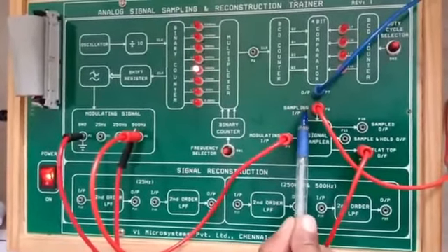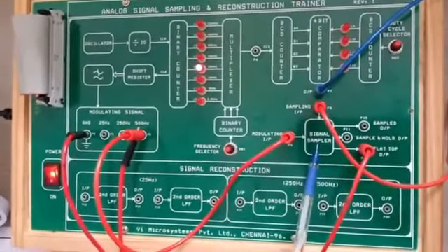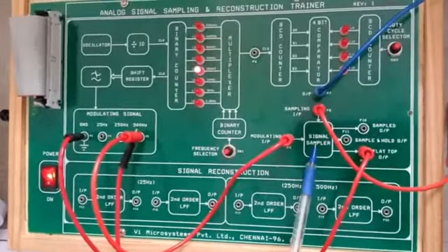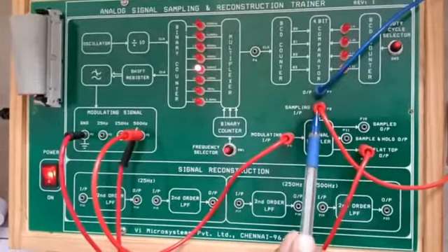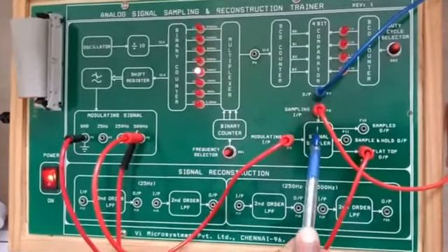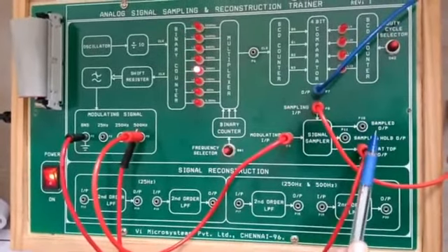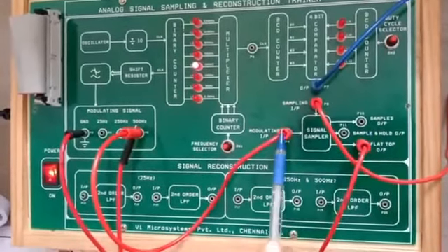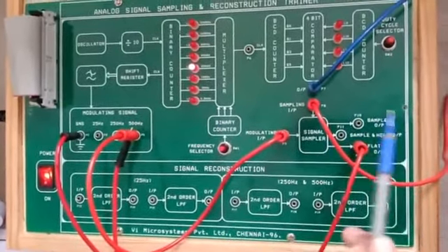What is a sampling pulse? A sampling pulse is a pulse used to actuate the signal sampler, because you already know the signal sampler is nothing but a switch. That switch is actuated with the help of the sampling pulse. Whenever the sampling pulse is present, the switch will be closed, and the input just reaches the output. Whenever the switch is open, there is no output; the input does not reach the output. In this way we convert the continuously varying signal into a discretized time signal.